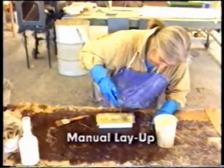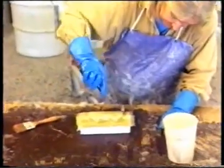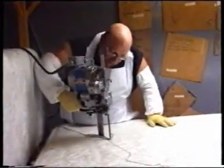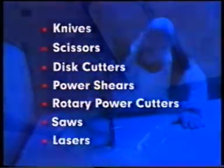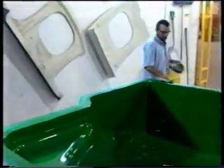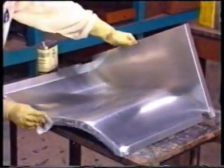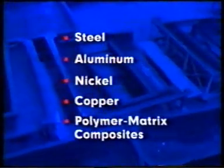Manual layup is a widely used method of manufacturing a wide range of composite parts and components. The process begins with cutting the reinforcement material to size. This may be performed using knives, scissors, disc cutters, power shears, rotary power cutters, saws, or lasers. A mold having the desired part shape is then coated with a release agent to permit subsequent part release. Composite manufacturing molds are commonly made of steel, aluminum, nickel, copper, or polymer matrix composites.